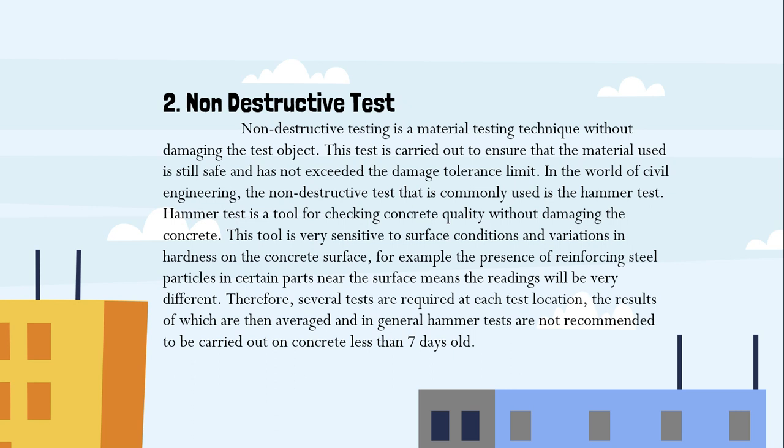In the world of civil engineering, the non-destructive test that is commonly used is the hammer test. Hammer test is a tool for checking concrete quality without damaging the concrete. This tool is very sensitive to surface condition and variation in hardness on the concrete surface.